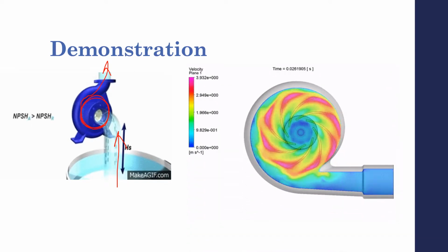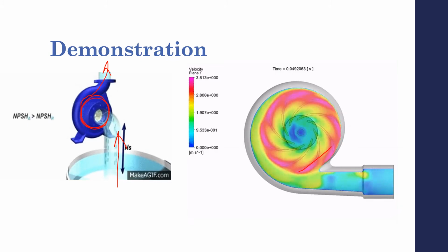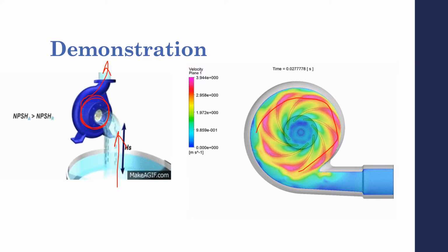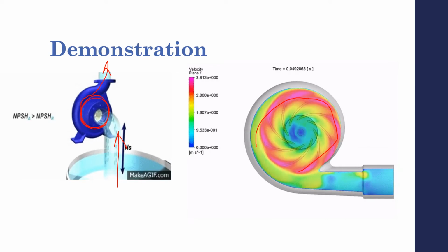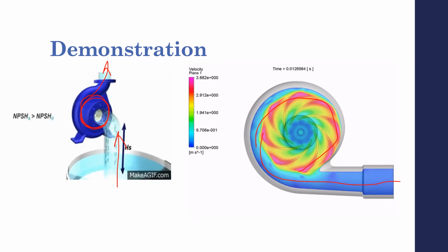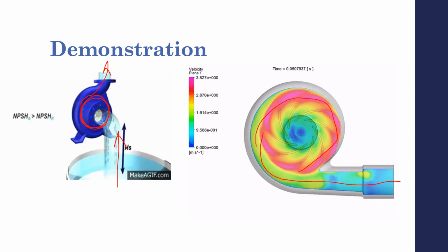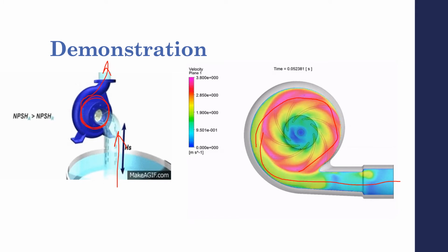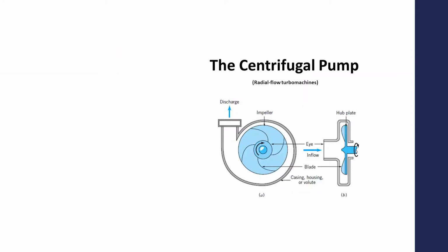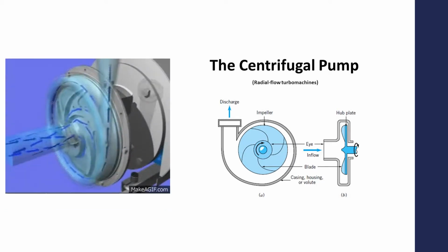This also describes the velocity scale, how the greater velocity is on the outer edges of the impeller blades going around through the centrifugal pump, which then exits the system, just as I said before. So within the increased velocity system, there's also a low pressure, which we'll also then explain through Bernoulli's equation later on in the slide. So another figure we have showing the centrifugal pump.